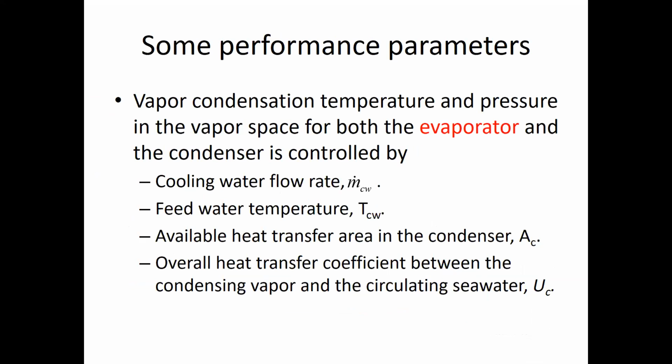Whenever we are dealing with systems like these, parameters we might be interested in include how much cooling water do you need from the sea to make sure all the vapor will condense in the condenser. What is going to be the T cooling water? So if you are talking about a desalination system of this type, which is located close to the sea, the point here becomes how much the performance is going to change from winter to summer.